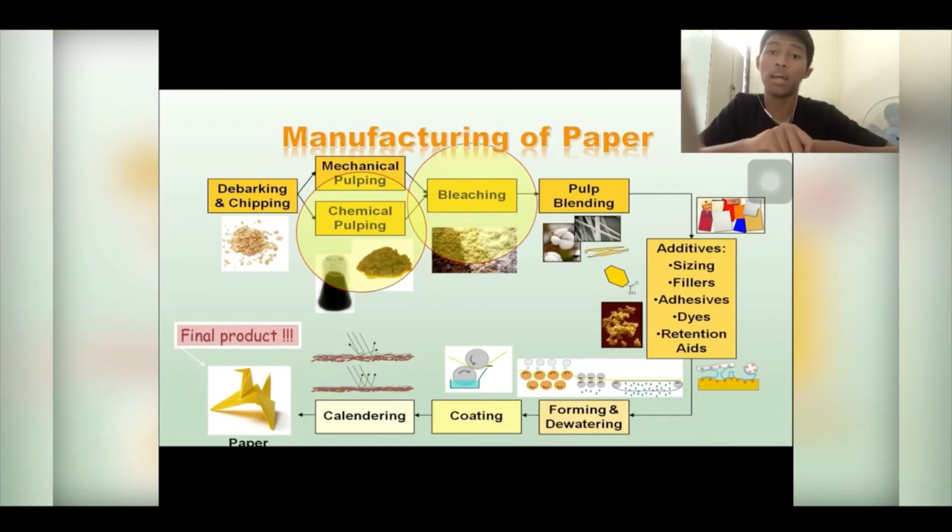So the second step is that the pulp is next put through a pounding and squeezing process called beating. Inside a large tub, the pulp is subjected to the effect of machine beaters. At this point, various filler materials can be added such as chalks, clays, or chemicals such as titanium oxide. These additives will influence the opacity and other qualities of the final product. For the third step, which is coating, pulp is fed into the machine on a moving belt of fine mesh screening.